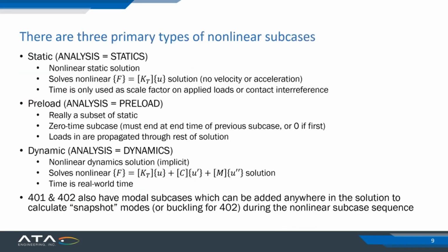In terms of that analysis equals statement, there are 3 primary types of nonlinear subcases that you'll be choosing from when you're setting that statement. So first and foremost is the analysis equals statics option, which is your nonlinear static solver. And that's basically solving the f equals kx type solution in the iterative nonlinear sense.